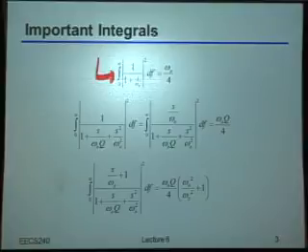Okay? So because of that, I've given you this cheat sheet that just tells you the answer from the get-go. As an example, if you had a very simple first-order low-pass filter, then it turns out the integral of this first-order low-pass filter is just omega naught over 4, where omega naught is the bandwidth of the filter. Now, by the way, the way you should interpret all of these integrals is, you remember I kept using that delta f in all of the expressions before? These integrals are really what actually tell you the effective bandwidth.